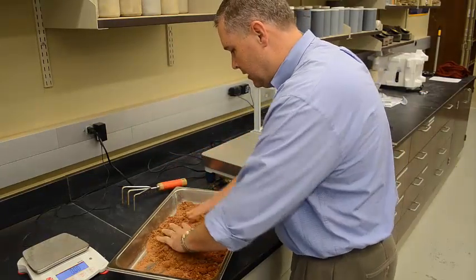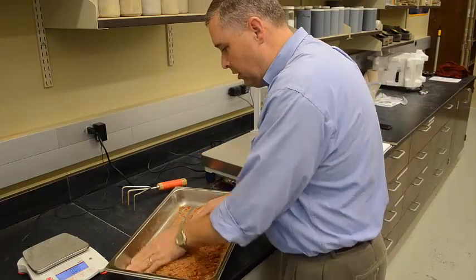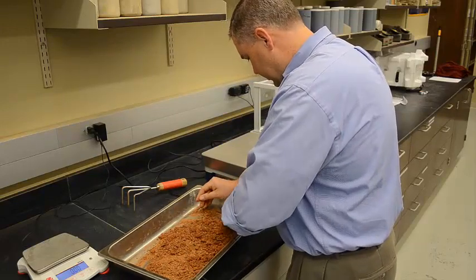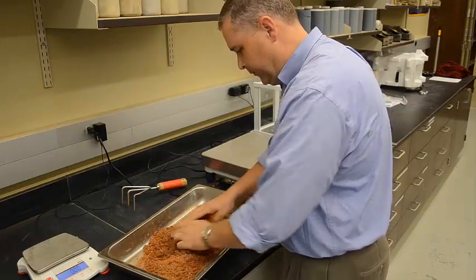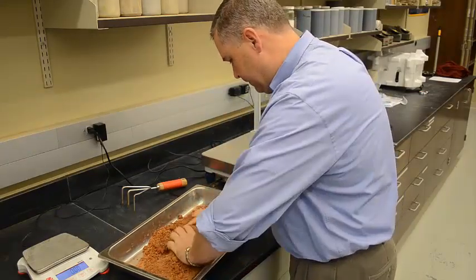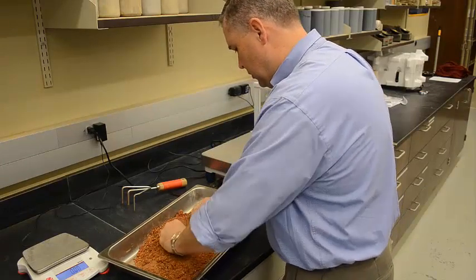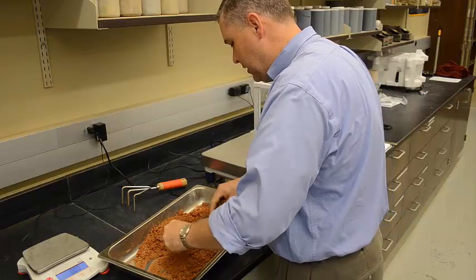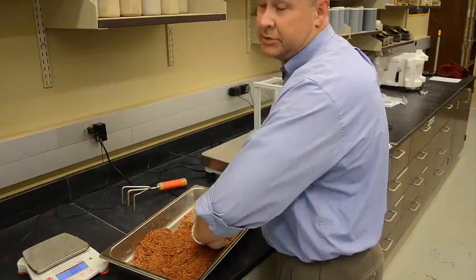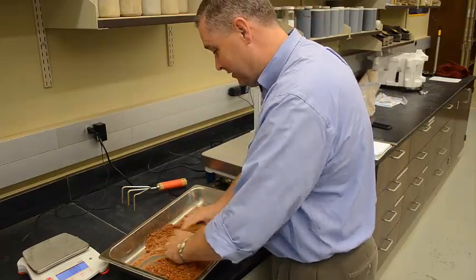And you can see that the easiest way to do that is to really just get your hands dirty, get in there and mix up the material very well. Most of the time this material here will be oven dried, which means it'll only have about 1% or 1.5% of moisture in it. So I would recommend starting with a dry material, adding about 6% moisture, 6.5% moisture to start, and then you add 2% on top of that for each point beyond.